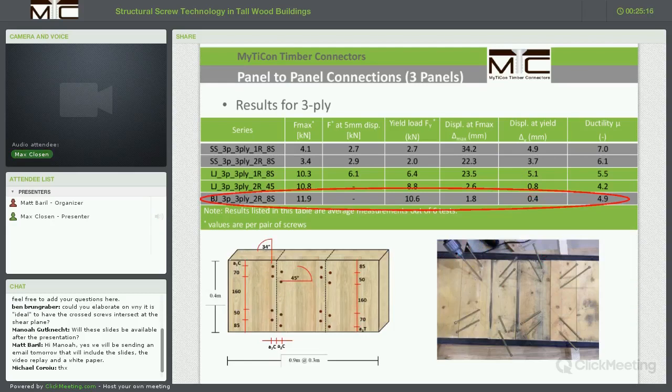It is again apparent that the screws are utilized in tension and therefore provide high capacities and high stiffnesses. For this particular set of testing, we could also allow for a force in this direction. The fasteners are basically driven in cross angles here, and could also allow for out of plane load transformation load transfer if required.